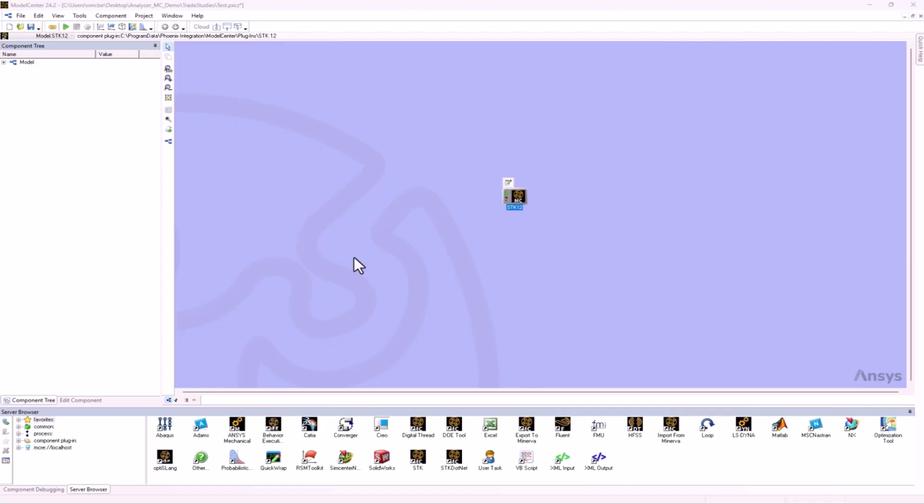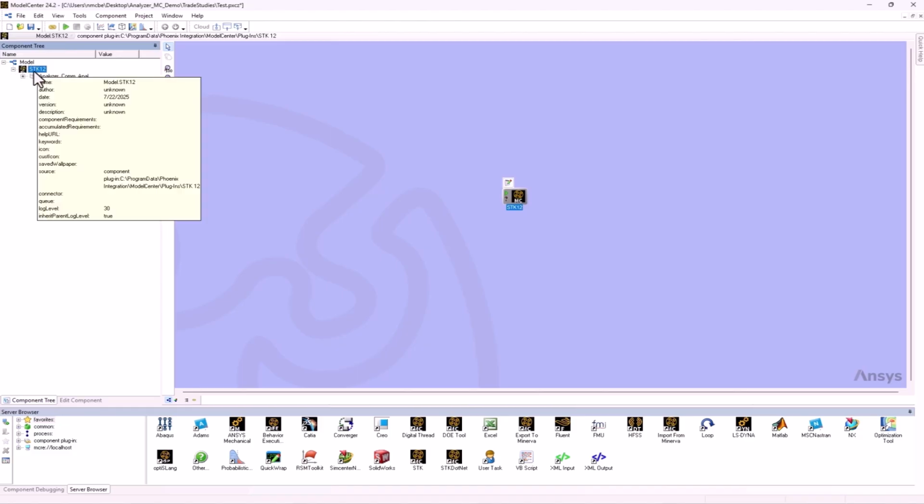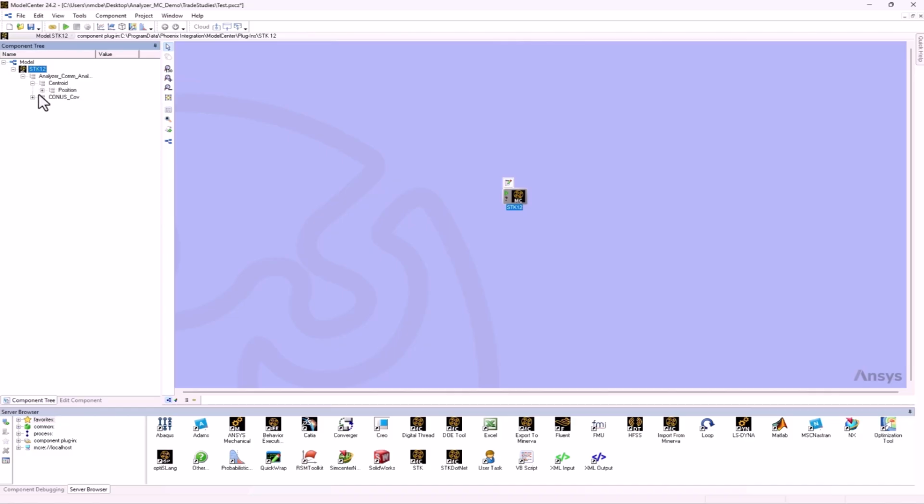All right, so I've set up that analyzer workflow very similar to what I had previously. Expand my model window, and you'll see that the only thing I have in my designer here is the STK block, but it's now exposing all of those inputs and outputs, the same ones that I had designed and created and linked previously. I haven't calculated anything yet. It's pulling what my current or previous STK scenario had for my latitude and longitude values, and if I'm interested in that average Eb/N0, you can see there's a red X indicating this hasn't yet been computed.